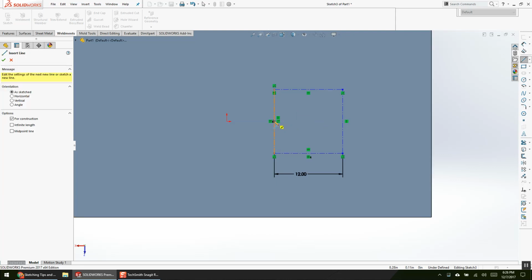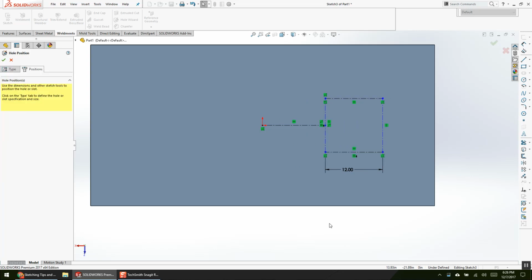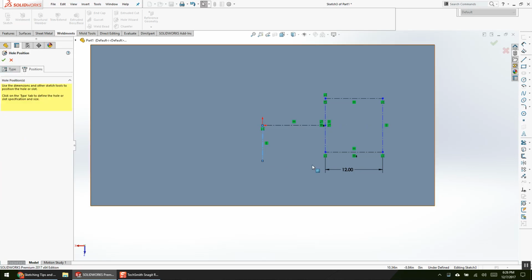Yep, so the next thing is, how do we intelligently get this placed where we want, and I still have another set of leg holes I need on the other side? So how are we going to limit our liabilities and have good design intent that's readable that I can hand off so other people can pick it up really easily? Mirror it. So what do I need to do to mirror it? I need another vertical line.